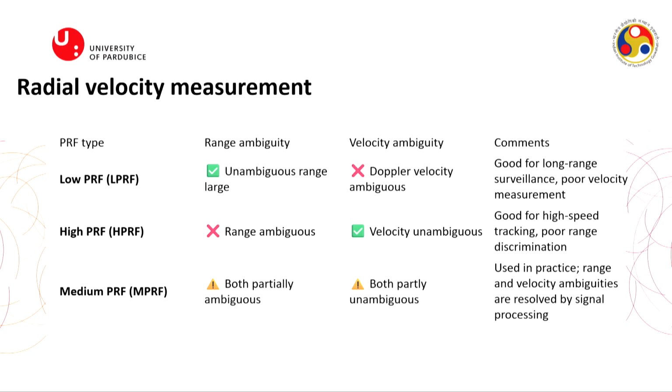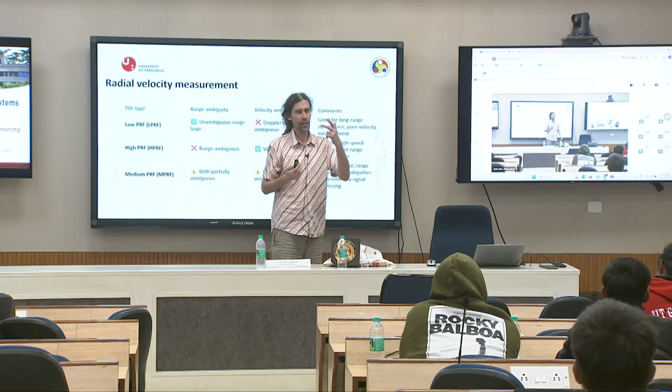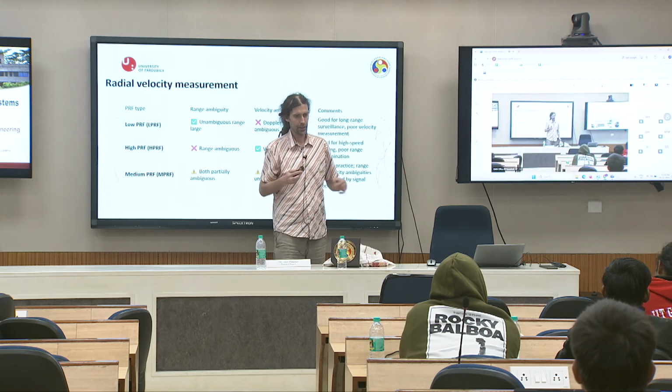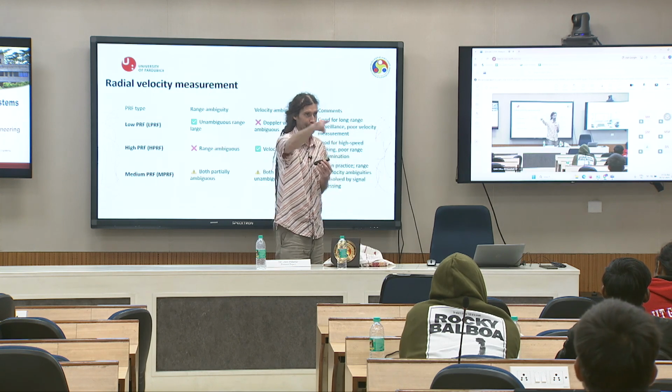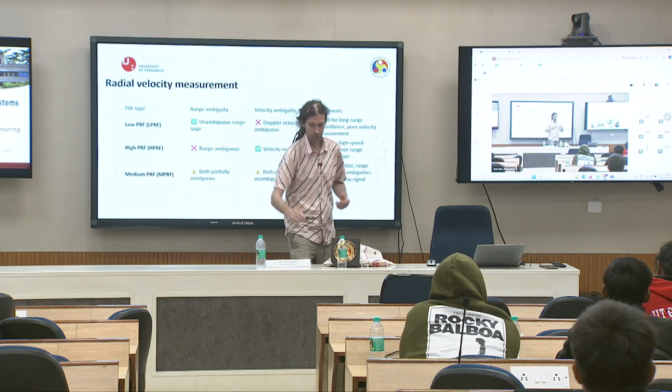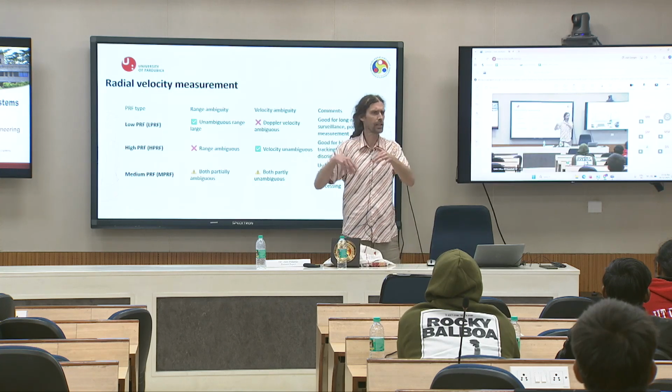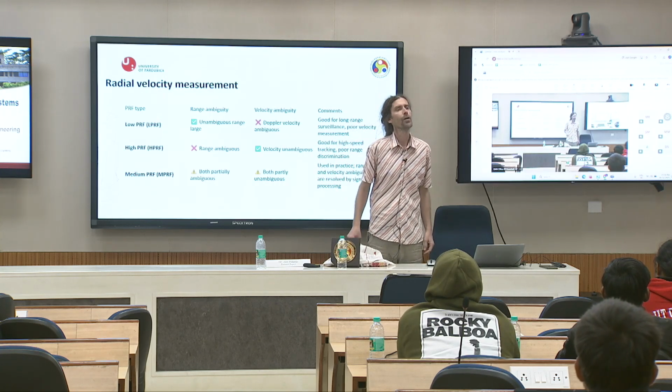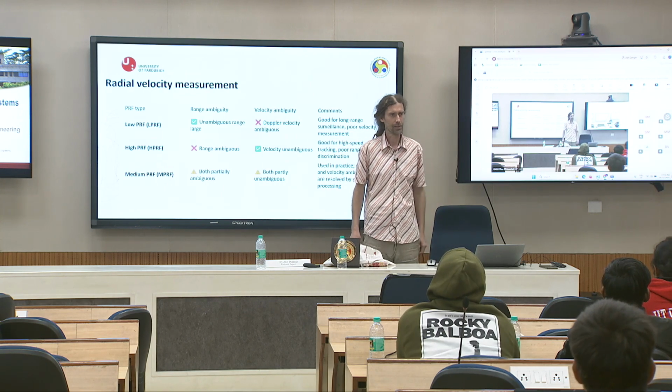So you need to have minimally 3 transmitters of opportunity, and from cross sections of all ellipses you will define where is target. But can you imagine how many cross sections will be there from 3 ellipses for one target? 2, 4, 6. Okay, one target.